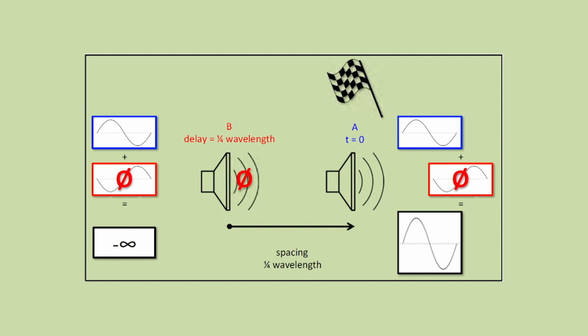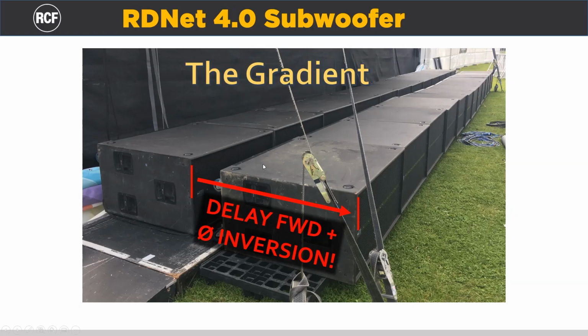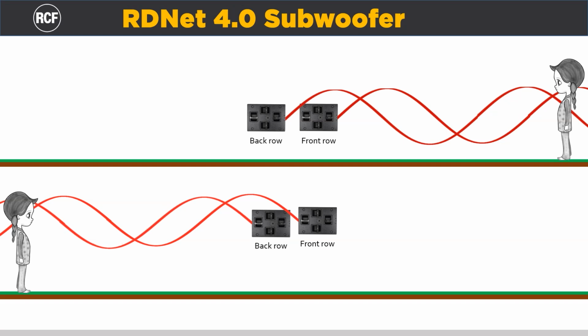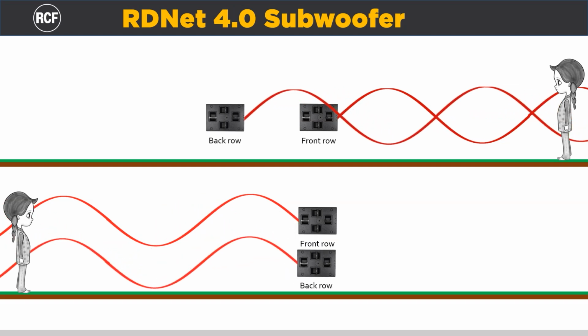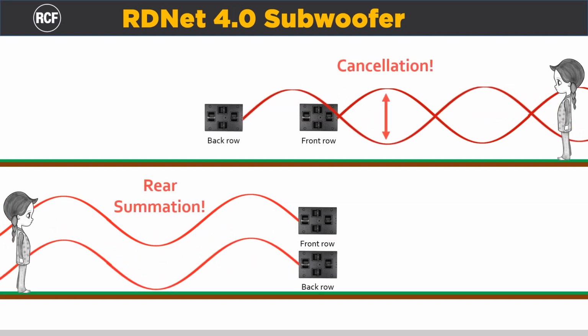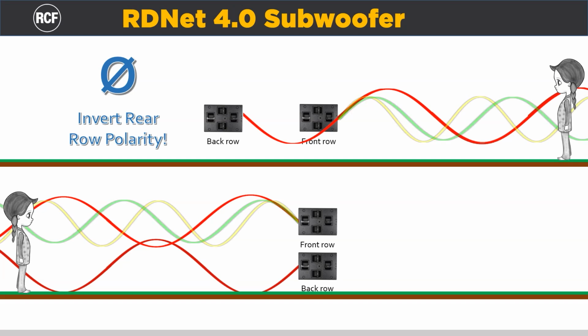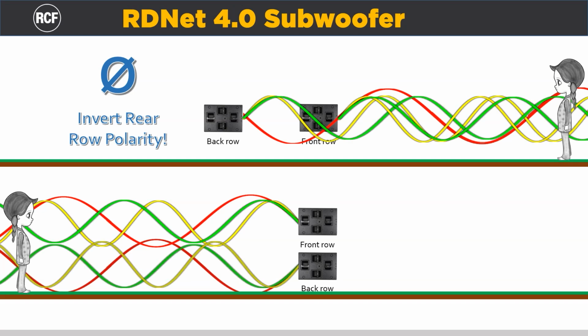Subwoofers in the gradient configuration have a polar pattern comparable to that of directional microphones. This means, unlike the end-fire configuration, cancellation will be present, so the cardioid effect, at all frequencies sent to the speakers. The gradient configuration represents the only way to control the polar pattern at low frequency and can provide, when properly set, useful patterns that allow the listening area to be shaped at low frequencies according to your needs.